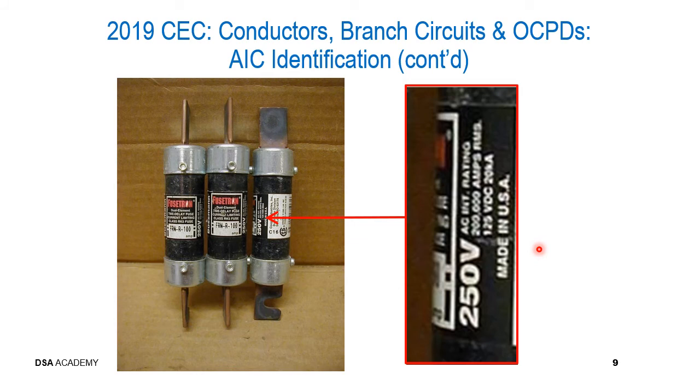Now the thing that I want you to pay special attention to is that if you look at these particular contacts, this one here on the bottom and this one here on the top, you can certainly see where there was a dramatic ground fault across this particular leg of this circuit. So much so that it's burnt away a large portion of this bottom contact, and you can see where it's basically attempted to spot weld the top contact. And again, it served its function. What it did was it opened up so that this fault current stopped flowing across this particular fuse.